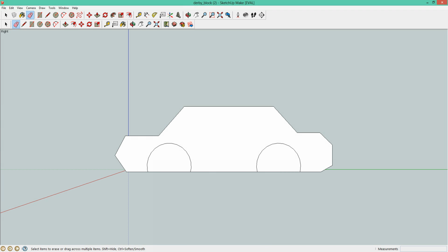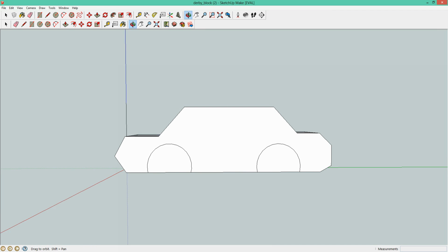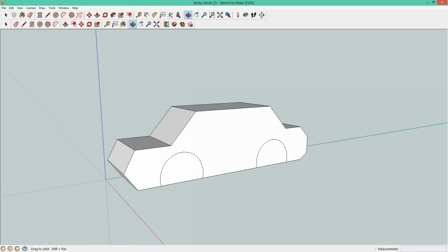Okay, next we are going to push these tires in. So what I like to do, just to get a different view on it, is go ahead and turn it, and again, we're going to be pushing these in. So I want you to take note of our measurements. So it tells you to go ahead and push them in at least a minimum of about 5 millimeters. So again, notice your distance down here when you're paying attention and pushing it in. So I will push it in, and again, it should say negative, around -5 or so. If it's a little bit off, that's fine. So mine is 5.3. Again, you want to make sure and do this 5.3 as well. Make sure that they match.